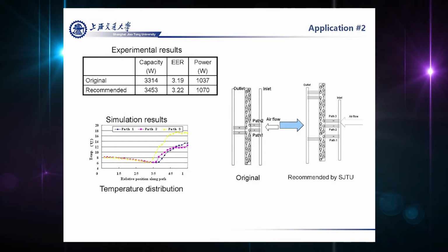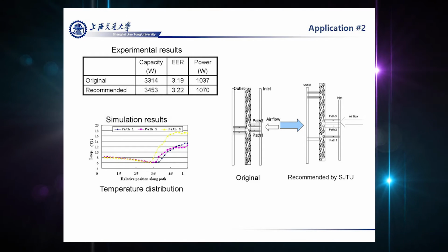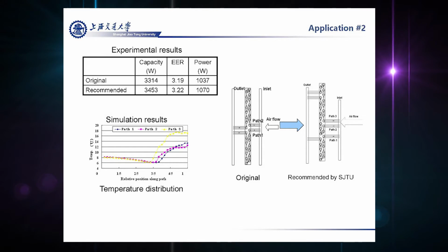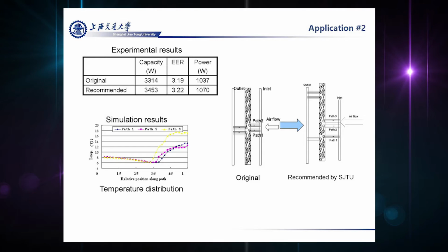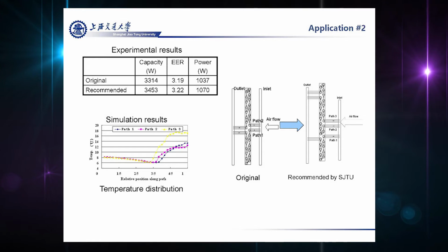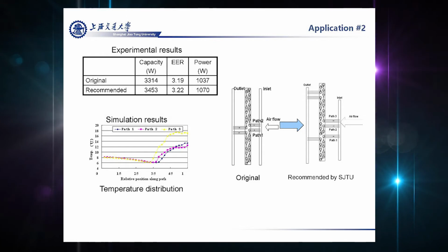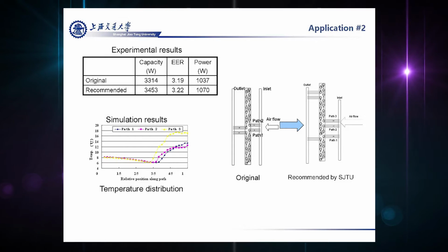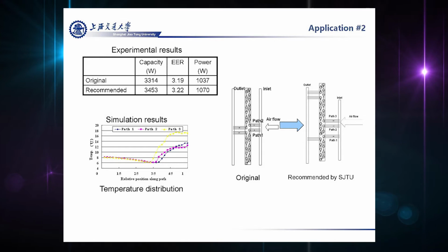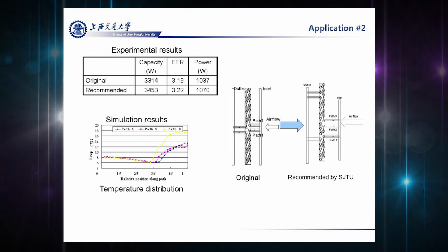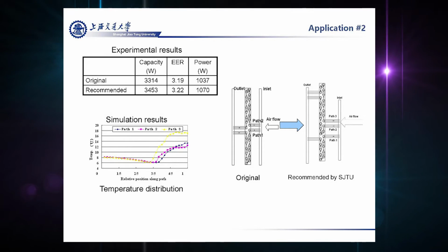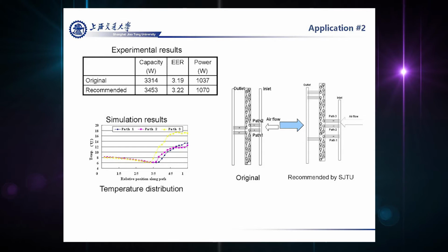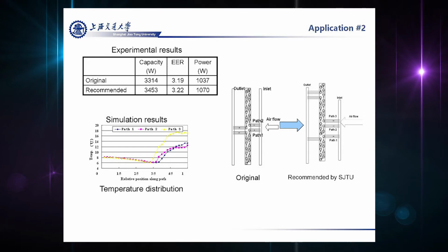We want each part of the heat exchanger to have almost the same vaporization point. At this point, all the refrigerant in the evaporator has evaporated, going from two-phase to gas, and we want this point to be the same for each circuit. So when designing this, we must be careful.